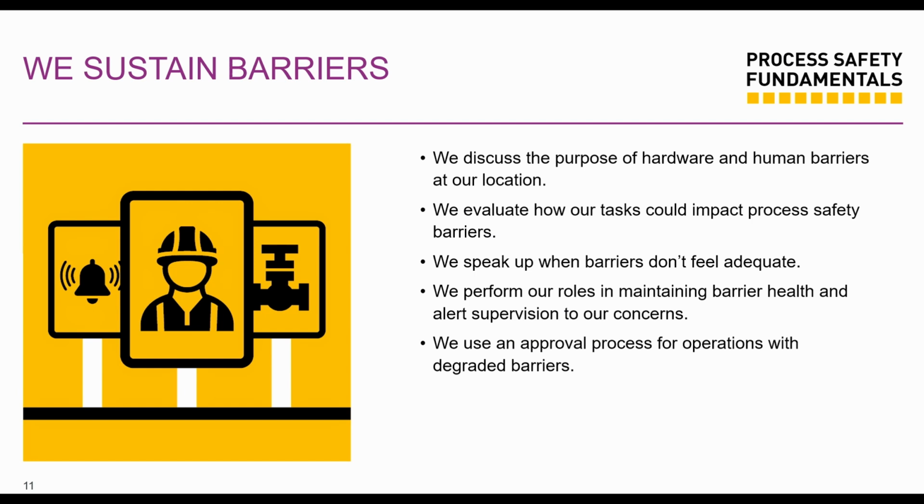Or you're so overwhelmed with a lot of work on sites. You don't have enough manpower to inspect all your PSVs, your statutory inspections, your yearly inspections of your PSVs. You leave them, and you don't run a couple of inspections on one of them or a few of them, because you don't want the downtime. But then you're operating and that PSV sticks. That PSV is actually a mechanical barrier to protect you